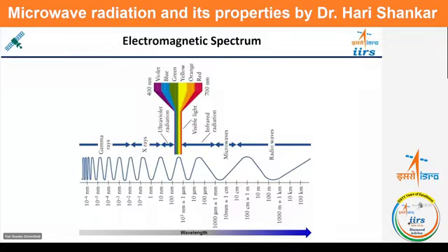But the radio waves, X-rays, ultraviolets, and gamma rays are all either absorbed or reflected by the atmosphere, and hence they cannot be used for remote sensing. Even between the visible portion and the microwave portion, we cannot use all the wavelengths, because a few wavelengths within this range are again absorbed or blocked by the atmosphere, and we cannot use those wavelengths for remote sensing.